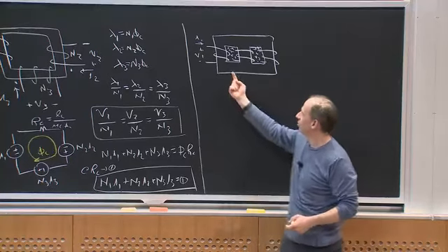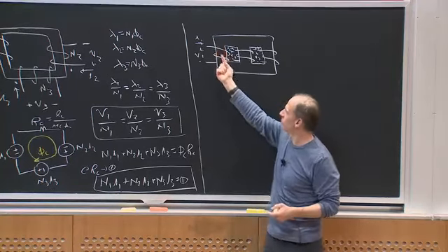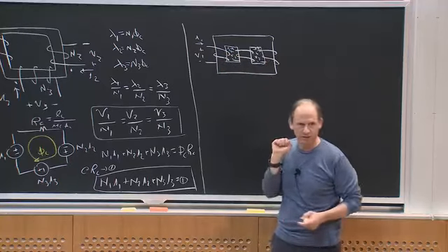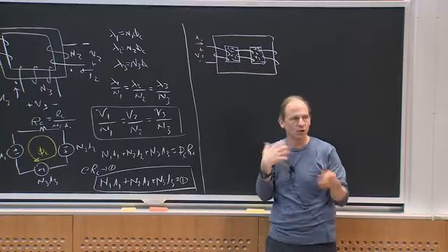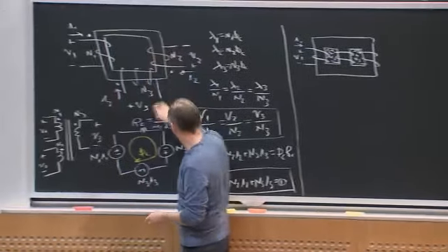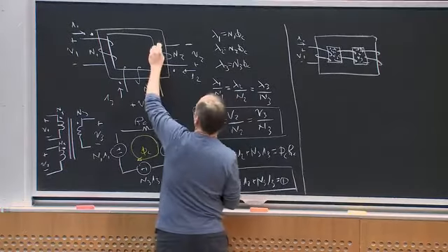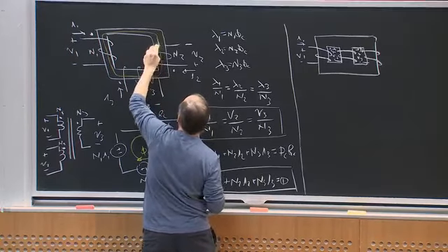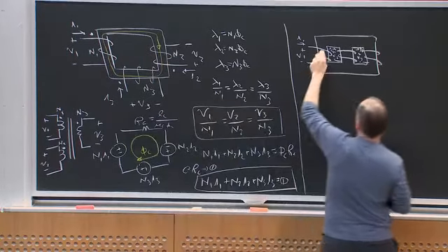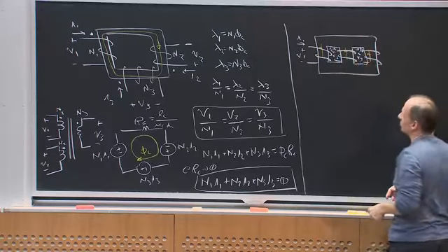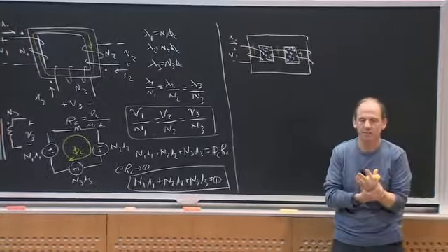That means that the flux going through this here, or the flux linkage here, isn't directly related to these 2 flux linkages. It's not one-to-one, it's not just scaled. Because here I only had one flux path going around the core. Ideally, here was my flux path, right? There's only one flux path. Here, there's a flux path here, and a different one here, and a different one here, and I get some constraints, but they're not the same fluxes.